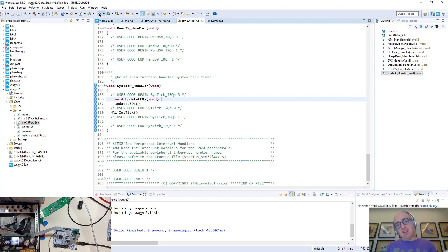I'm going to do a bunch of work that takes long enough that it actually starts making the SysTick handler be a bit wobbly, and it beats against the SysTick handler as that happens. So basically, I realized that the DMA callback for audio is absolutely rock solid, right? Because it's every 64 samples. So it actually serves as a better low frequency clock. In fact, 64 samples is like 1.5 milliseconds to 2 milliseconds, depending on your sample rate. So SysTick handler for now, while we have no audio, but I'm actually going to move this into the audio callback. But fundamentally, you can do your UI here, read your buttons, nice and regular.